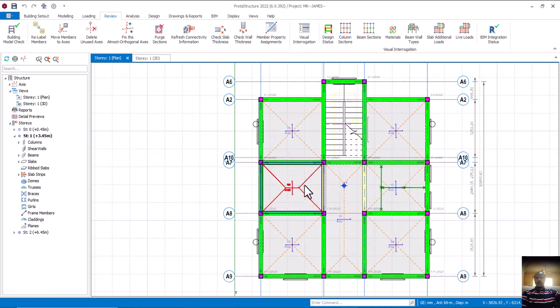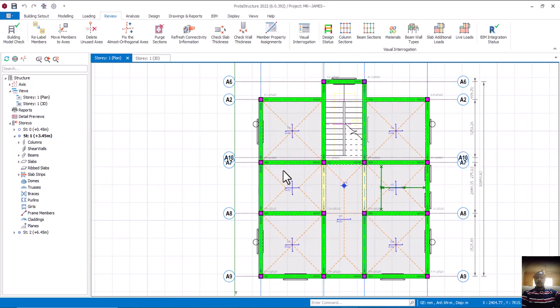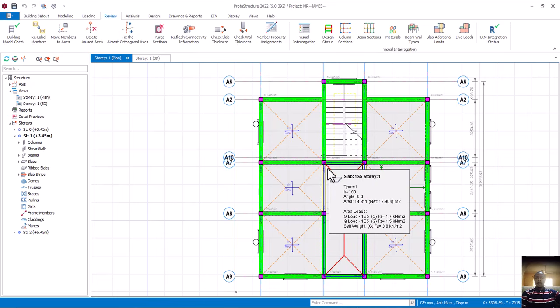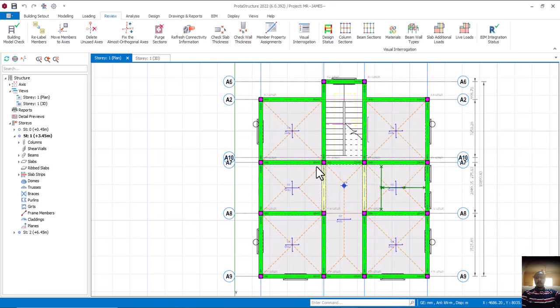When a hinge is introduced to any joint, what does that mean? The moment at that hinged end becomes 0. Is that okay? So the software will now know that this particular place has been hinged. Now the reinforcement in that place is also reduced, the number of reinforcement bars. Is that okay? So now let's go there.